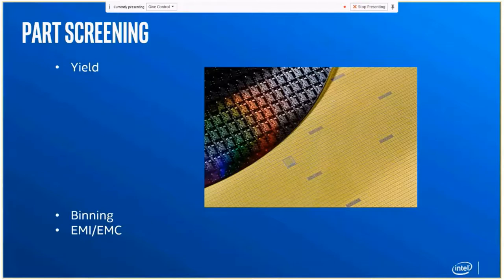Like what's happening, right? We do those kinds of tests, and there is also thermal testing. So there are heat chambers. You put the device inside and get connections out. You may just be making sure the cores are up, or maybe you may be sending 40 gig traffic and looping it back, right?